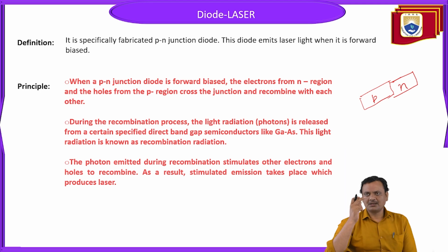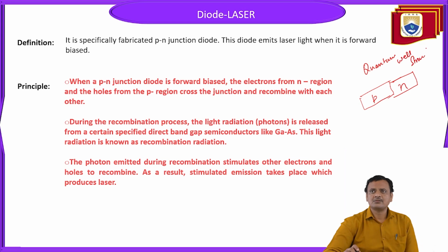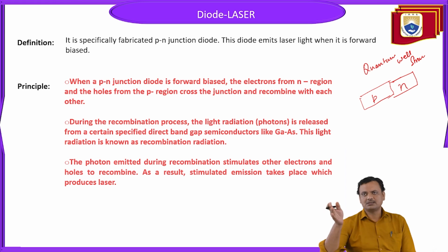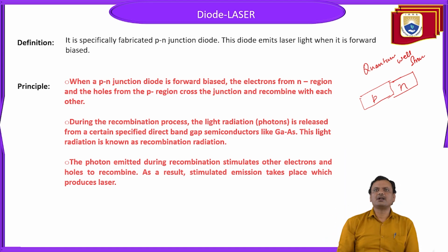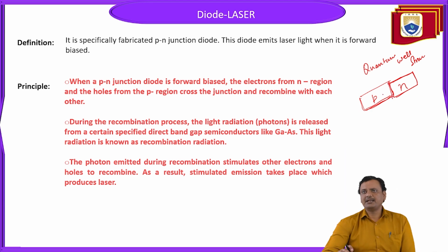Once I was discussing the quantum well structure. What did I tell, what is a quantum well? If you confine one region, one direction of any semiconductor crystal or any crystal, the entire property of the crystal will change due to the confinement effect. So for manipulating or band gap tuning, you can choose the width of your available crystal. And you can also dope these available p-type and n-type semiconductors up to a certain doping concentration, so that you are able to achieve the phenomenon of population inversion.